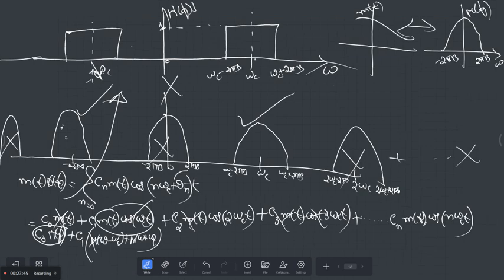I told you, this is the replica of that. It's not two band pass filters. Whenever you draw a band pass filter in frequency domain, whatever is there on this side, the same thing will come on this side. This is because of the symmetry property. Drawing only one-sided is not correct when you draw the Fourier transform. The other side also will be there because of the symmetric property. Have you understood this? Okay?